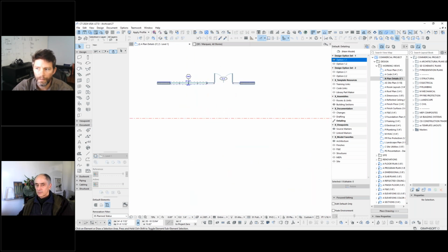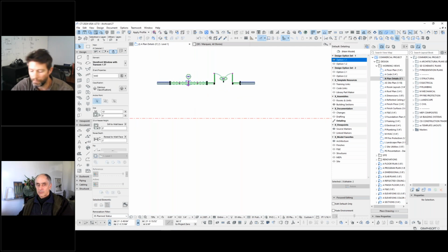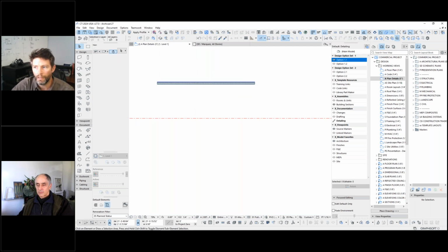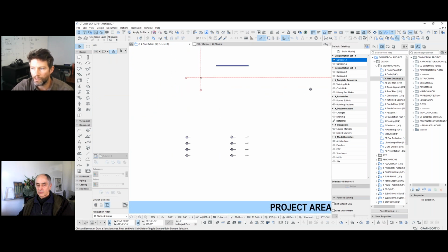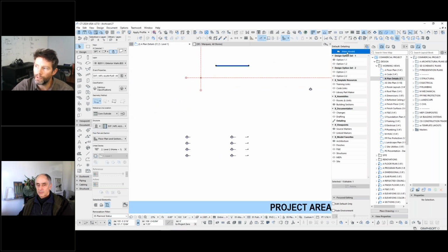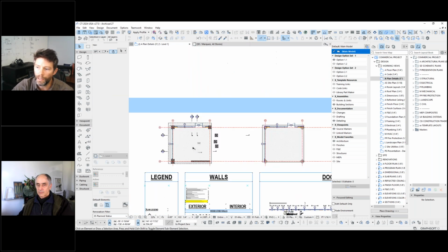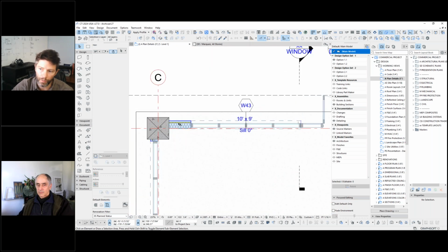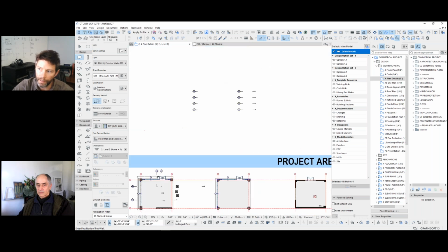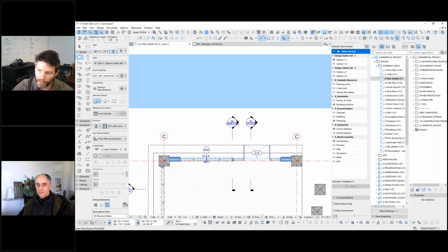We can test that. So I don't believe so, because it's mainly just, let's do this for example. So this wall here is associated with the main model. So that would be kind of our active. If we eyedropper, I think it was this wall that I picked it from. So we pick up those settings, and because this one here, if we select this, you can see that that's assigned to this building sections assembly.